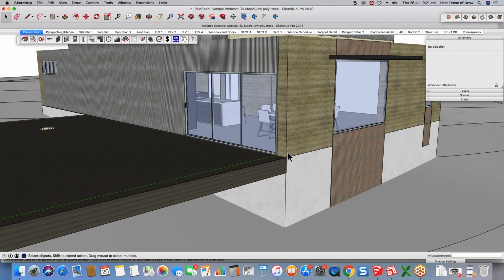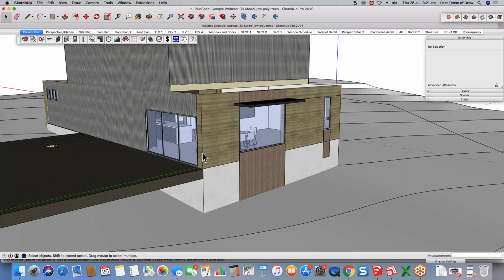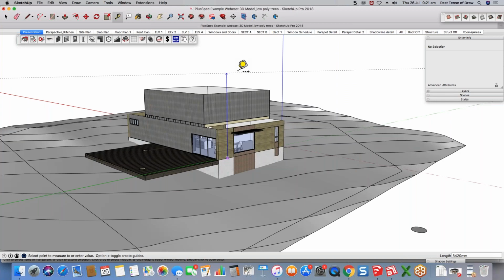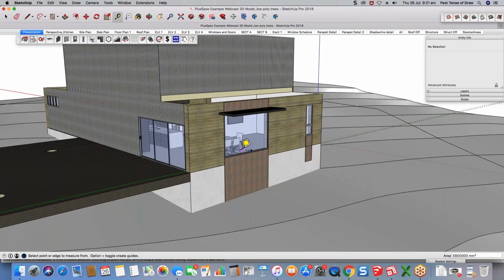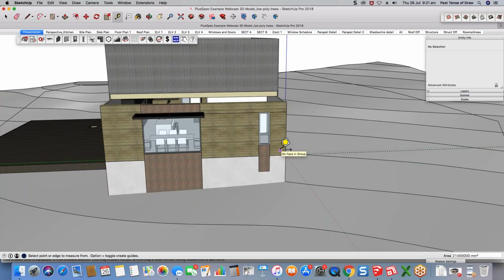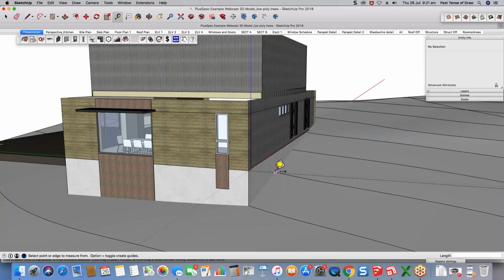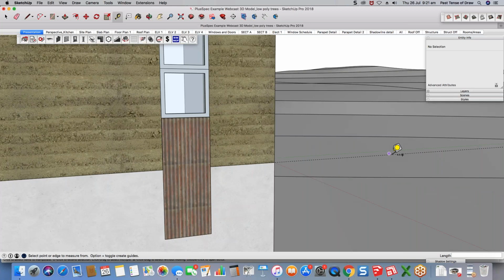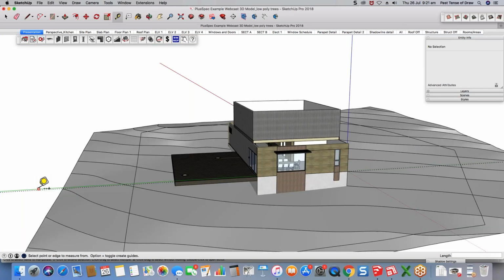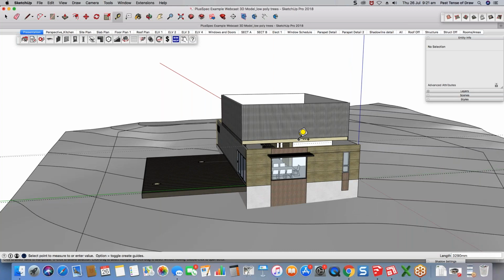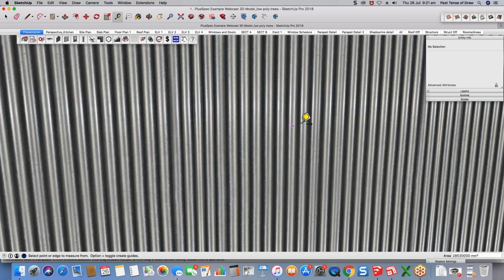Then you can set a tape measure tool, and the tape measure tool enables you to set these little guides or grids, and you can do them on the vertical. So for example, what I can do now that I've set my first one, I can now grab it again. So I'm just going to left click on the actual guide, and then I can bring it up on the blue axis, hold down shift, and then I can decide where I want it to be. Do I want it to be, for example, to this sheeting? And I've now got my second level.